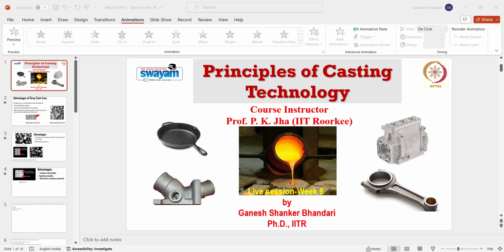So when you apply some stress on the material, the iron carbide is going to resist. Through ferrite you are going to move freely, but when the stress reaches the iron carbide layer, it is going to resist that. So you are going to get better toughness in the system.